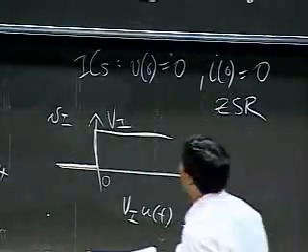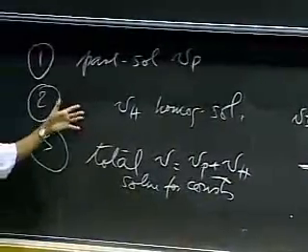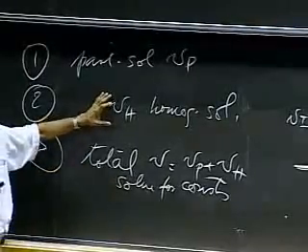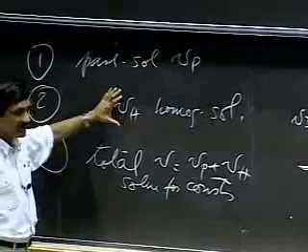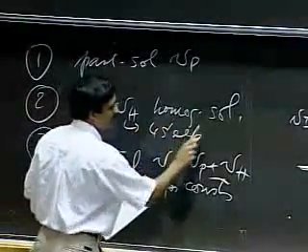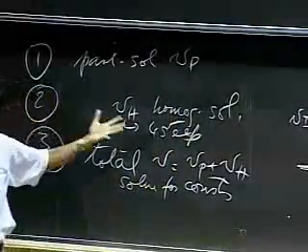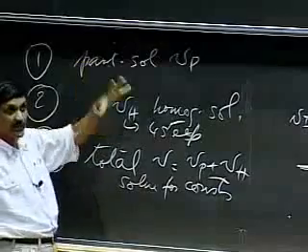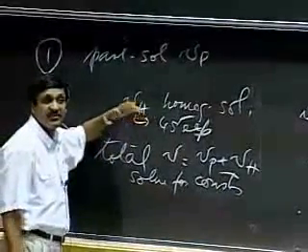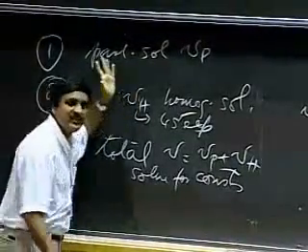So more math now. Three steps: particular solution, homogeneous solution, total solution, constants. It's almost like a mantra here, like a chorus. Homogeneous solution we compute using a 4-step method. And the 4-step method for homogeneous solutions, it turns out, happens to be that way for all the equations we'll see in our course. The first step is to assume a solution of the form A e raised to st, exactly as with RCs.